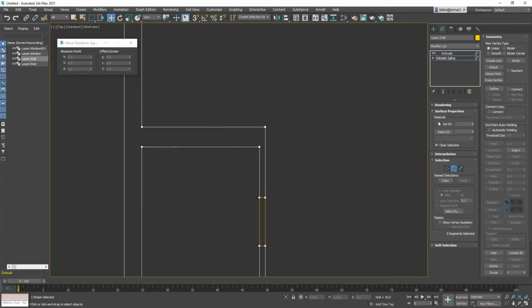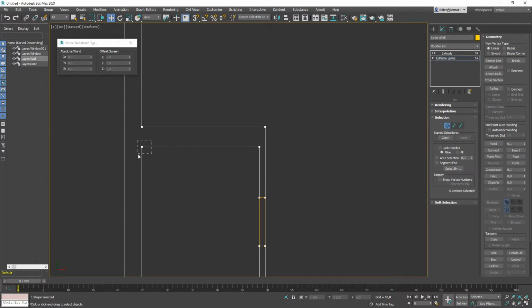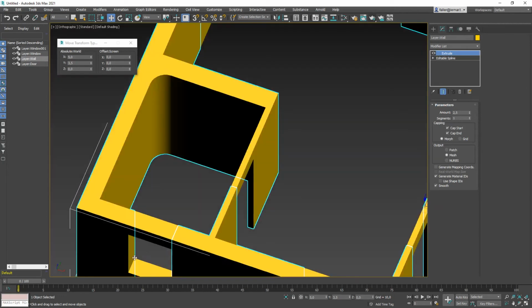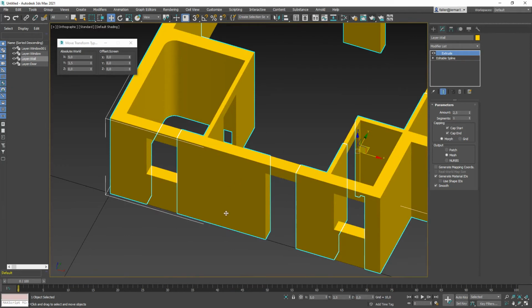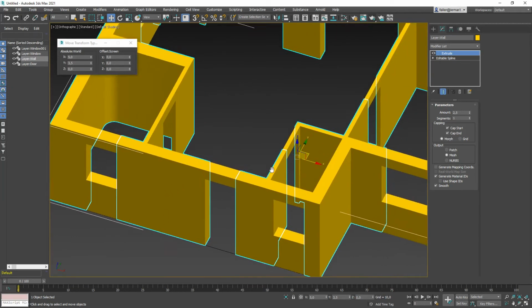I can also select in vertex level. Let's say I select this vertex. Something I haven't shown you here is a button called fillet, and that basically allows you to round this corner without using a Bezier point, because rounding creates 2 points, and the two lines perfectly stay the same. So here we are. Let's get out of the vertex level and back into the extrusion, and here's my change. So the lines, they stay editable by simply going back in the stack.